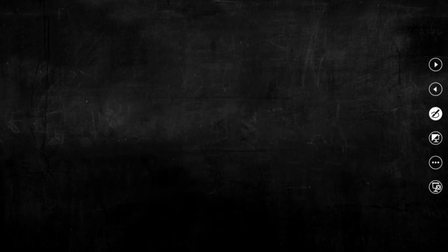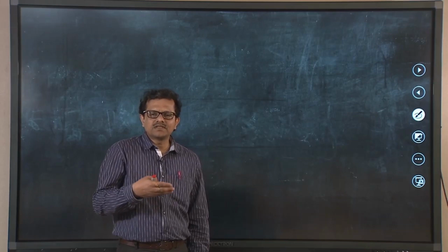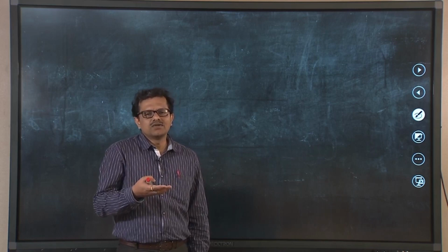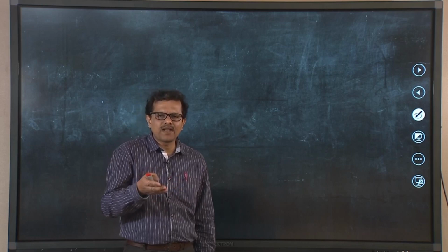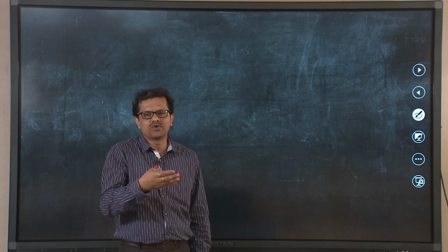Okay. So, now let us discuss the compression efficiencies. In one of the previous classes, we talked about the isentropic efficiency of the compressor. We had seen that a degree of irreversibility is present in the compression process, and for that reason the actual work that should be supplied to the compressor for the compression of the working fluid would be more.